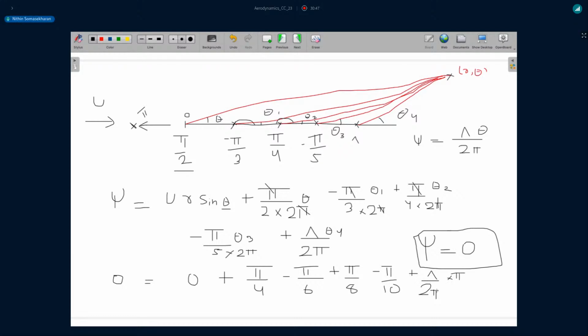So I cancel out these two pi's. All right, and then if I calculate all these and then find what my kappa value is, it would turn out to be around minus 0.8. All right, this should be the value of my source strength at this location, such that this kind of an assembly of sources will resemble that of a Rankine full body and create closed streamlines.